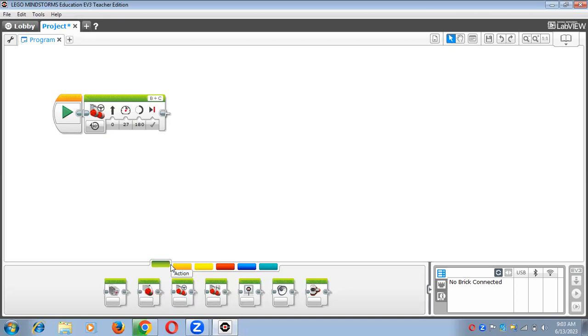One more thing I will tell you, if you are doing this programming in this software, you have to check your motor ports as well, because you know very well in EV3 brick we have two kinds of ports, A, B, C and D. These are the motor ports, and 1, 2, 3 and 4, these are the sensor ports.